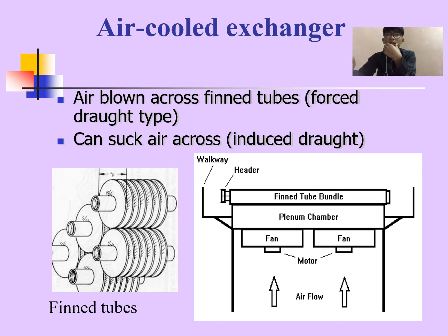In a heat exchanger cooled by ordinary air, the surrounding air is forced or driven by a fan or fans to flow vertically across the horizontal tube section. For condensation, the packaging may be tilted or vertical. Similarly, for a heat exchanger cooled with relatively small air, the airflow may be horizontal across a group of vertical tubes.